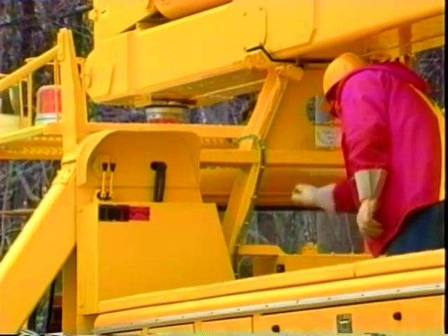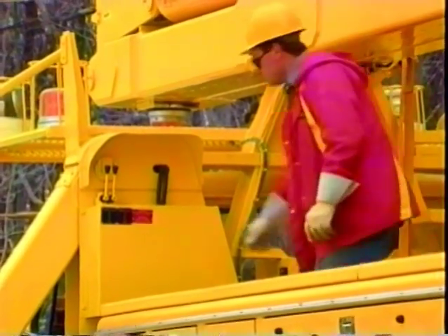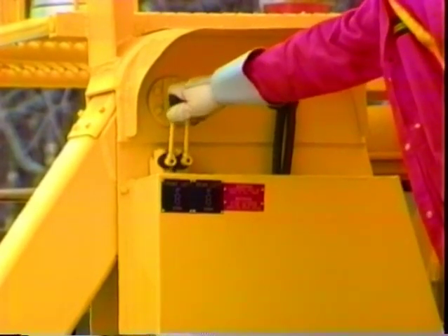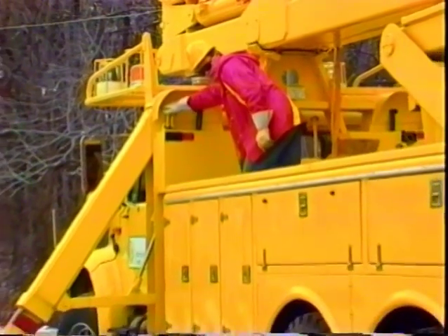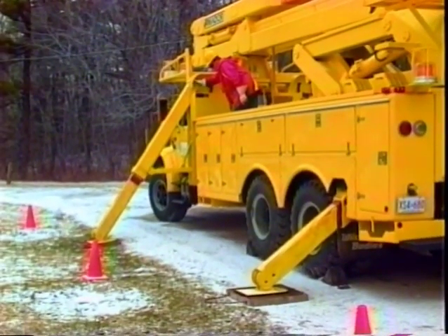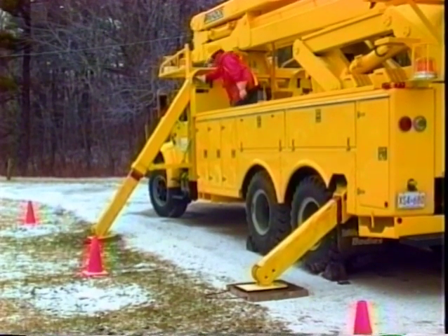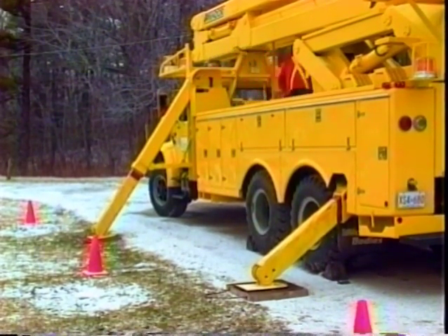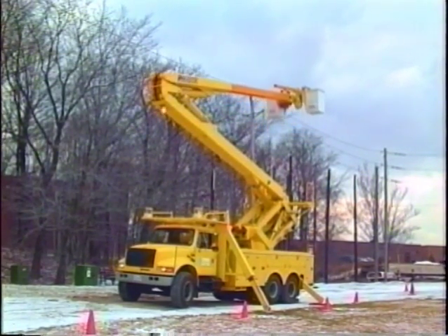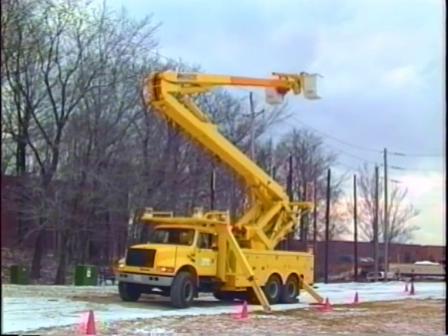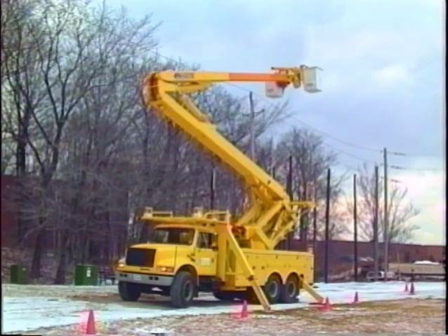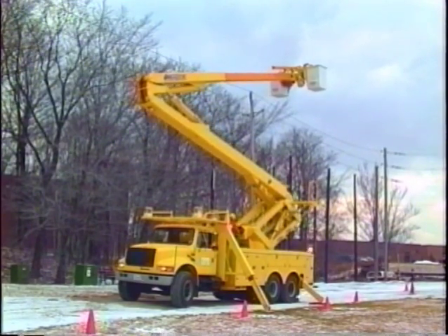Now you are ready to check the outrigger holding valves. With the outriggers still extended, turn the engine off or move the selector valve to disengage the outriggers. Activate the controls for 15 to 20 seconds. The outriggers should not retract. After checking the outriggers, restart the engine if necessary and put the hydraulic system through its paces. What you are doing now is purging the system, getting rid of any air, and freeing up the check balls in the holding valves.